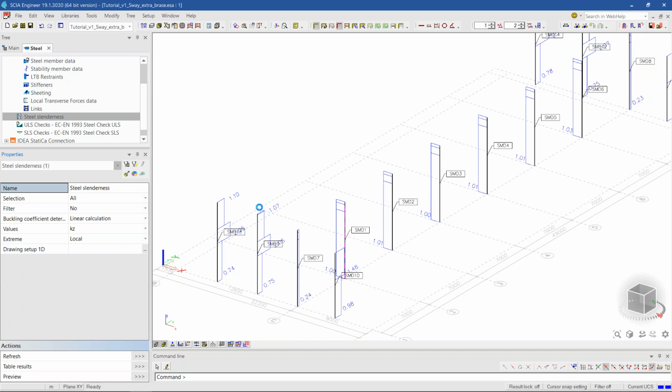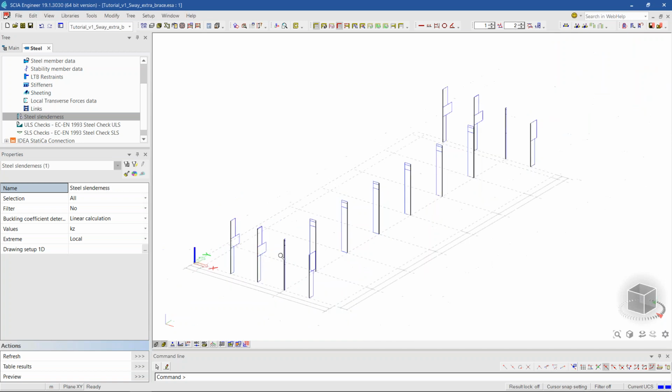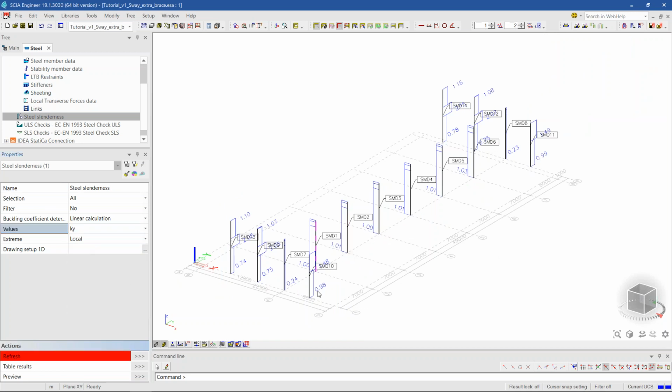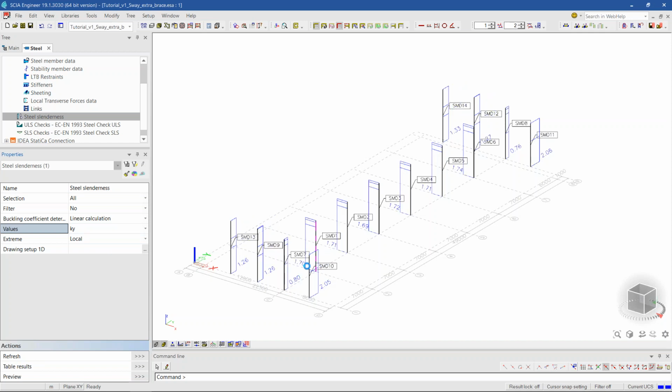Usually this problem doesn't happen if you have a buckling shape which is in fact supported by these lateral restraints. And so the first pitfall of this method is that it's asking me about the KY factors, and at this moment I don't even have the buckling shapes to assign to it so that it correctly will determine them. And you will see here 1.7 instead of 1, what I would expect, or something less than 1.